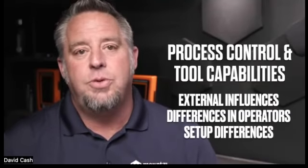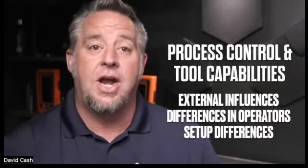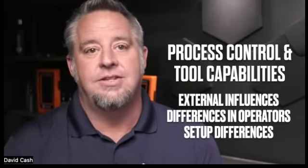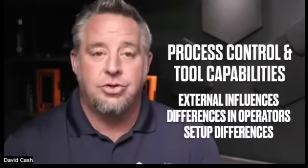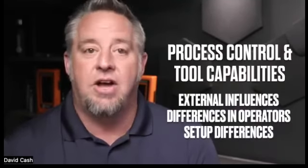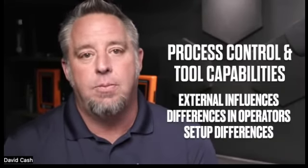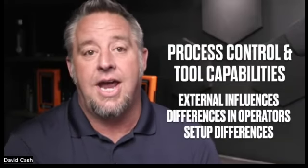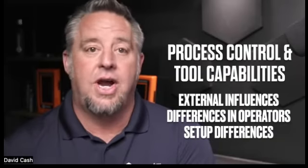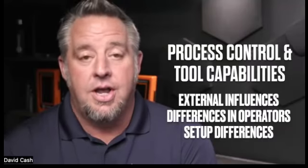So it really can help give you a direction on what you need to do to try to improve the process. That would be when you are using the CP and CPK measuring of your actual process versus measuring the tool itself. But when you do the CM and CMK testing, again, this can really help guide you in taking a look at your process and what you might want to try to address first to help tighten up those particular numbers.